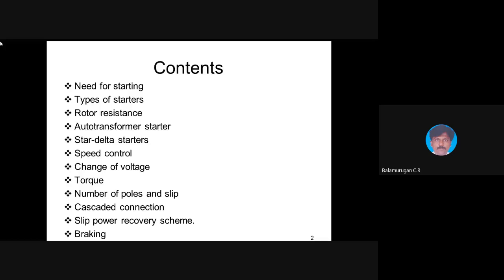So as per the AC system, how will you limit the starting current? You won't add any external resistance in the squirrel cage. We reduce only the supply voltage, and automatically the rotor current developed due to the reduced voltage will be less. When the rotor starts to rotate, you gradually increase the voltage, and when you apply the full voltage, the rotor runs at maximum speed. This is the concept: reduce the voltage and then increase it gradually, so that the rotor current is limited.